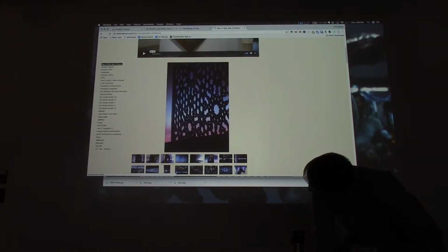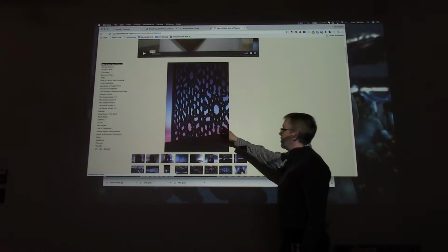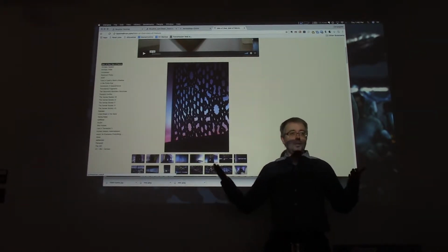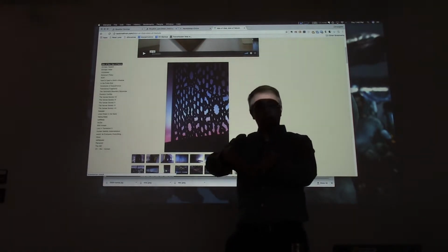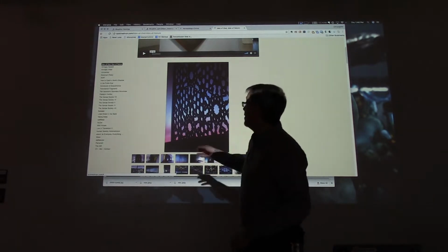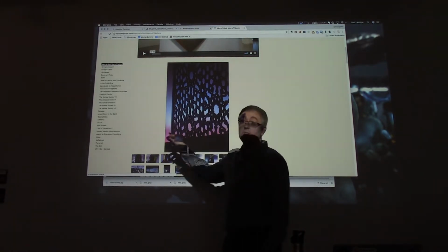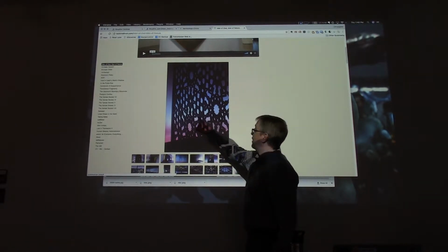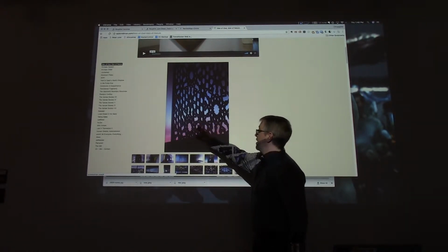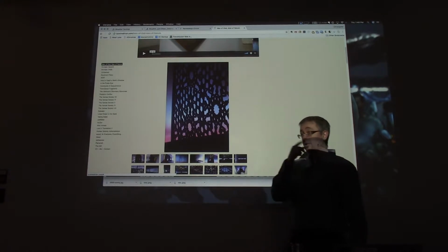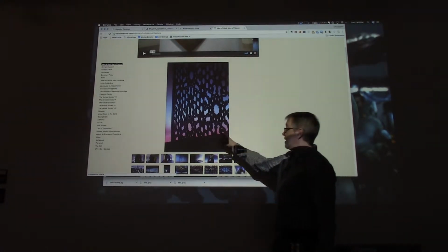The extruded ABS. And so in this case, we've actually carved this, we cut it with what's known as a V-tip. And so it's just like a 45-degree cone that you use for cutting. And so then everything you cut with it has this bevel, this V bevel. And so this is all one path. It would cut out this shape and then cut out this and cut out this, and so on and so forth.